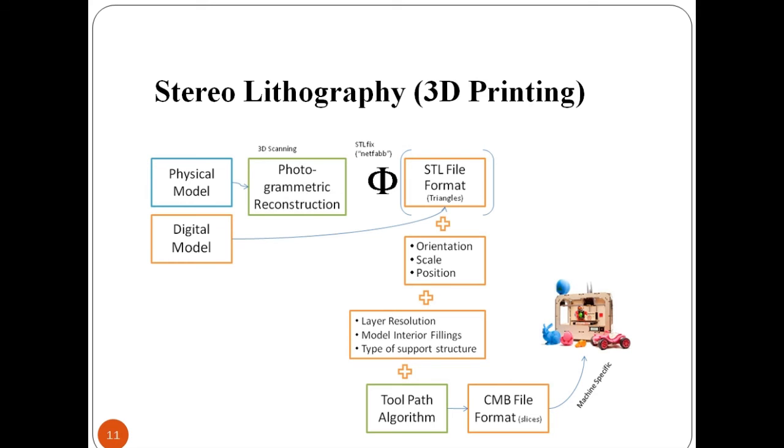The perforated platform is then lowered very slightly and another slice is traced out and hardened by the laser. Another slice is then created and then another until a complete object has been printed and can be removed from the vat of photopolymer, drained of excess liquid.